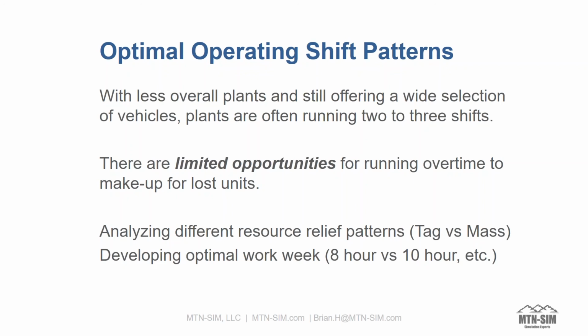If you were trying to do this deterministically, it's going to peter out very quickly. So in the simulation world, we can really test out various build schedule patterns and sequences, and we can come up with the most optimal release pattern that gets us close enough to our original customer order, but also achieves our overall throughput targets.